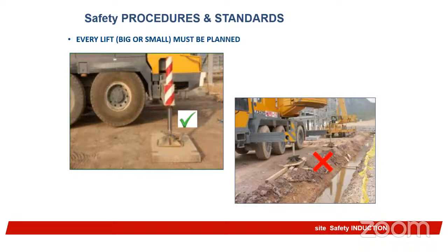Then talking about lifting, this is another. If you have a contractor, a worker whose job is to carry out lifting operations, then you can go into detail. Talk about the procedures for lifting. Talk about having a permit to work. Talk about the basic things you should know about: your outriggers, the inspection of the equipment, checking for hydraulic leakages, understanding the procedures to carry out the lifting, knowing the weight of the object you want to lift, the direction you want to lift, the positioning, and every other thing that has to do with lifting operations.